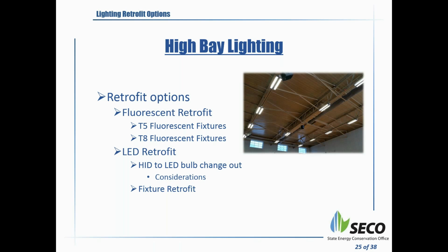So the considerations are that, and also you need to consider if the existing ballast in that HID fixture is old, then you will have a lot of problems with it, and you'll have to change that ballast anyway. So it might be better to do it at one time, change the whole fixture, because it costs a lot of money to get up there and do those retrofits. So the fixture retrofit traditionally is coming out pretty good. You have a lot of options over there. If you've got older HIDs in those fixtures, basically the best thing to do is a fixture retrofit.